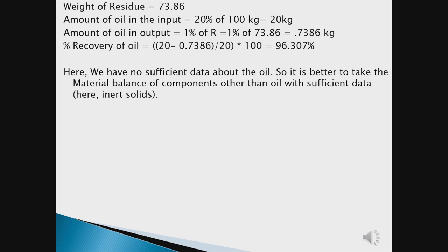Here we have no sufficient data about the oil, so it is better to make the material balance of components other than oil, with sufficient data. Just to indicate, if any key component is given in the question, it is always better to take the material balance of the key components, because whatever is given in the input as a key component should be received from the product as a key component.